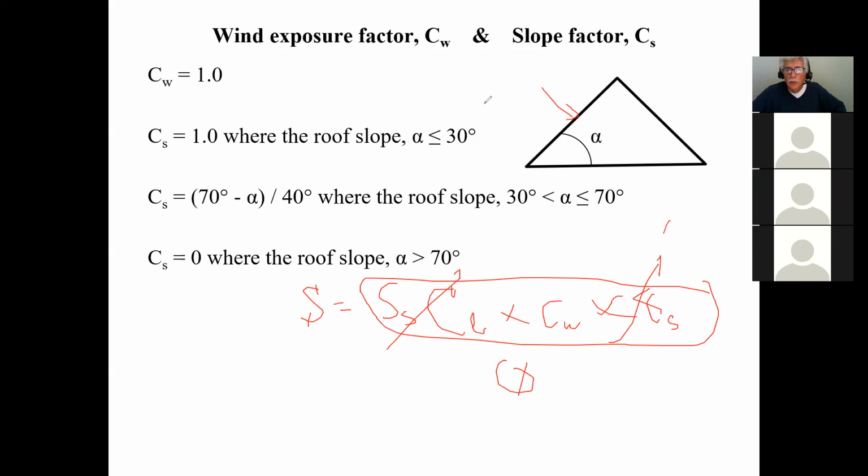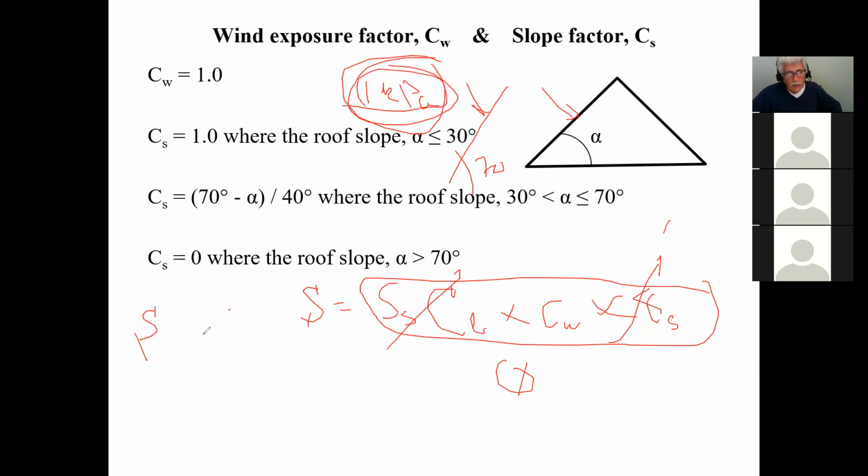Well, in that case, when the roof exceeds 70 degrees, remember what we talked about last week, that the minimum roof load is 1 kPa. We saw that on the table. I know you guys don't remember it. That's where you have to apply at least 1 kPa so that when the workers go up here, they can safely work on the roof without it collapsing under their weight. So that's the minimum load that you design a roof for. If ever I do my snow load calculation and it's less than 1.0 kPa, you should use 1.0 kPa minimum. So keep that in mind.